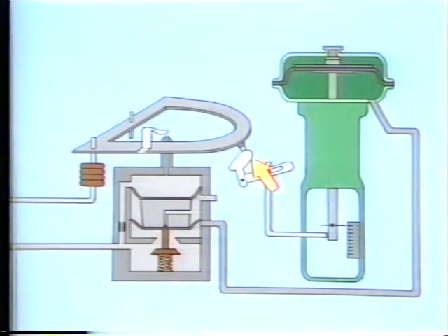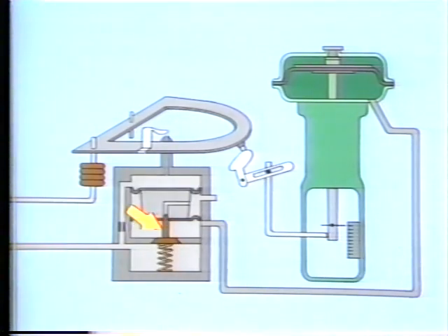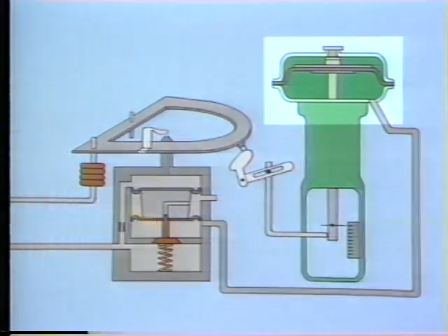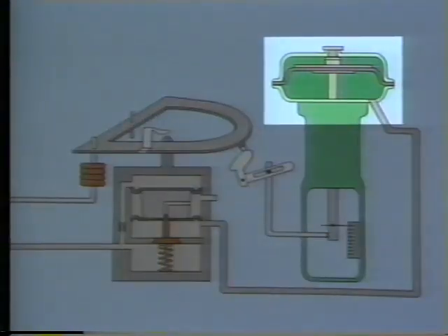When the motion of the cam balances the motion of the bellows, the flapper is positioned so that the relay plug shuts off the flow of supply air to the actuator. This stops the diaphragm assembly from moving and holds it in position until the controller sends a new signal to the positioner.